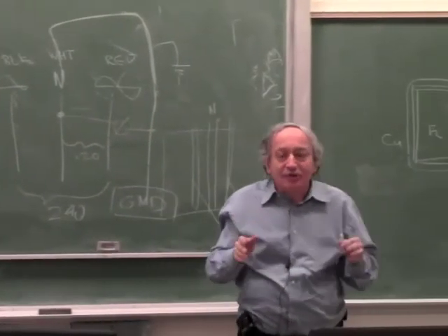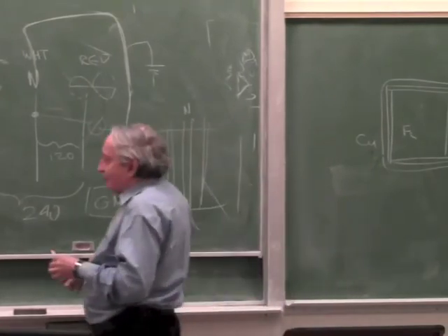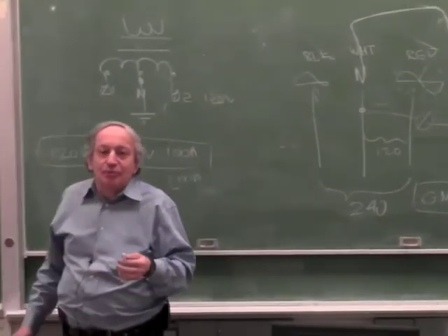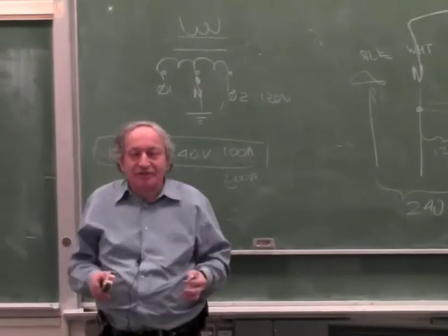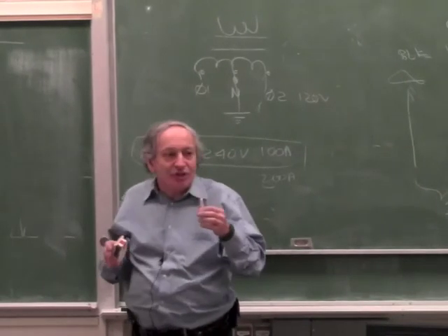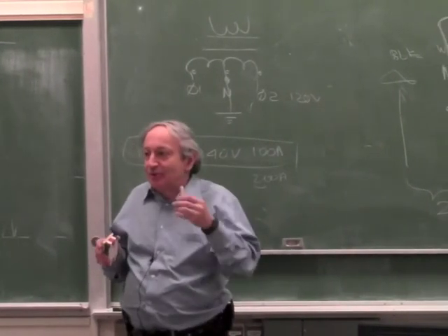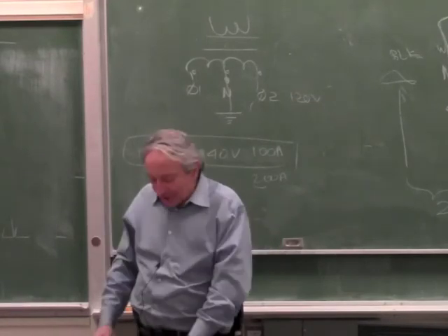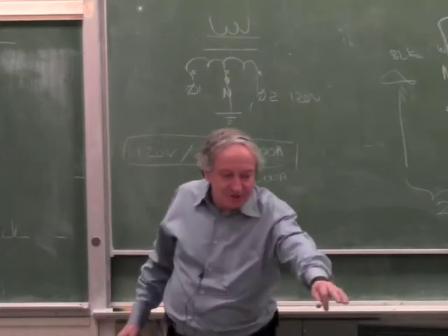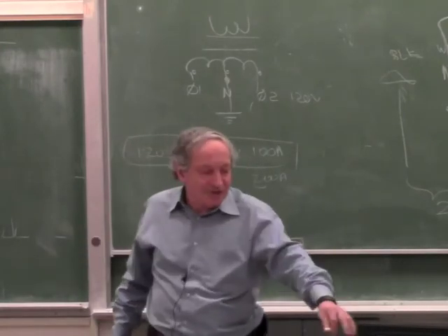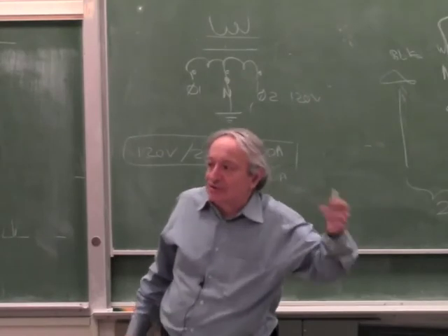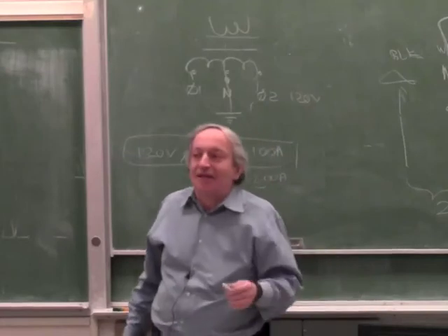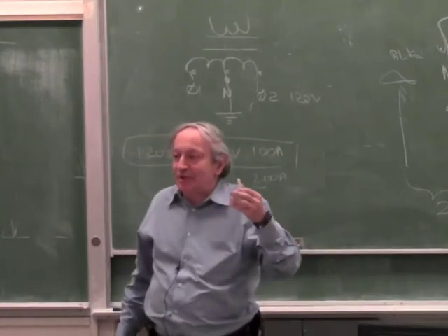Okay. What you want in a house is that if there is a short in the wiring or a short in the appliance, which makes the metal case of the appliance go live, you don't want it to be allowed. You want to blow the breaker, right? Otherwise, when you touch the case, you'll be killed, because you are connected to ground. If the case of this computer were touching the live wire, and I touch the metallic part, the current will go through me to ground. So I don't want to allow the case of anything metallic to become live, live meaning having a potential relative to ground.